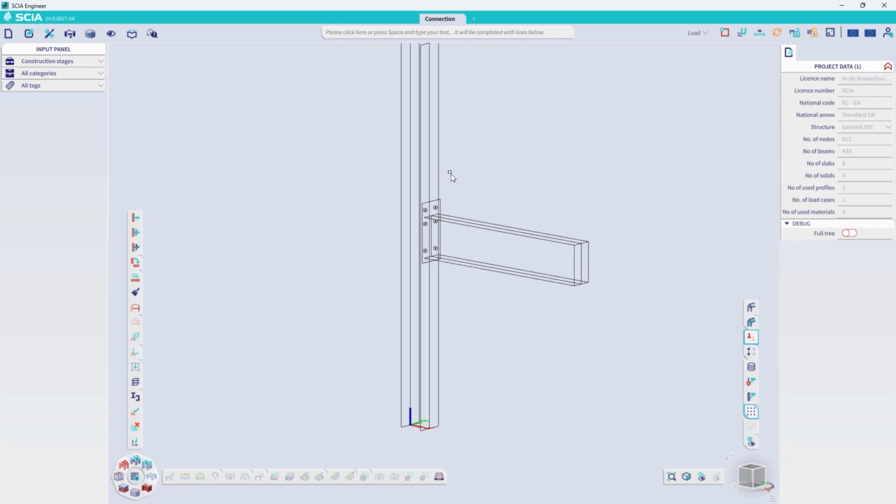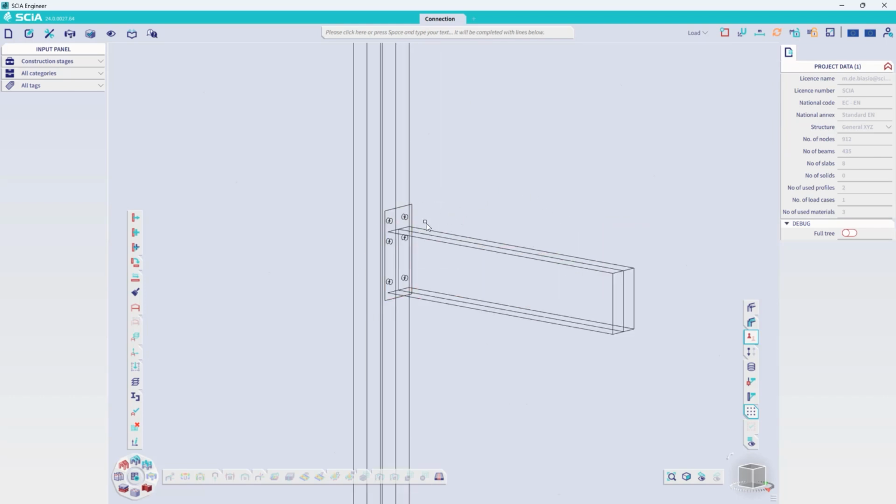In order to do so, as you all know, the only way that we can use is to make a finer mesh. The problem is that if I do a finer mesh everywhere, it's useless, because having a very fine mesh in the upper and lower part of the column or here far in the beam doesn't bring me accuracy where I want. On the other side, it also increases the computational time. So what I would like is to have a finer mesh only in the place where it's needed, that is, where I have most of the stresses.